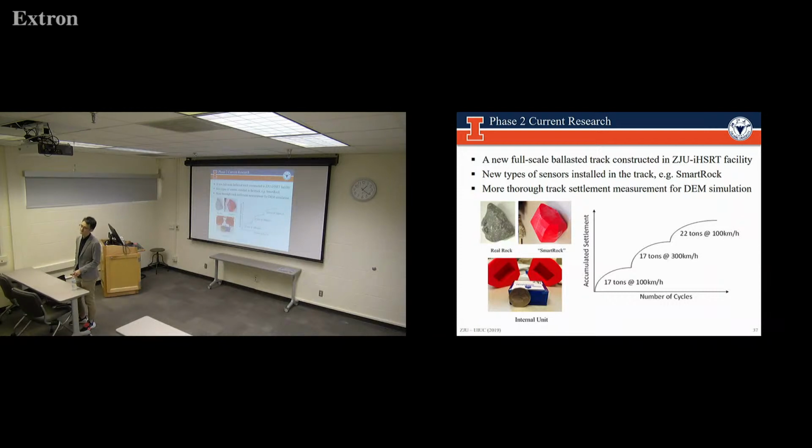Like, they have stabilizers, right? When they put in new ballast, they come and do the stabilizer shaking, and then some guy decides that that's enough. Okay, it's done. But what does that mean? How do you measure it? It's like by experience: okay, it's done, let's move on. So we don't know what the void ratio or density is.